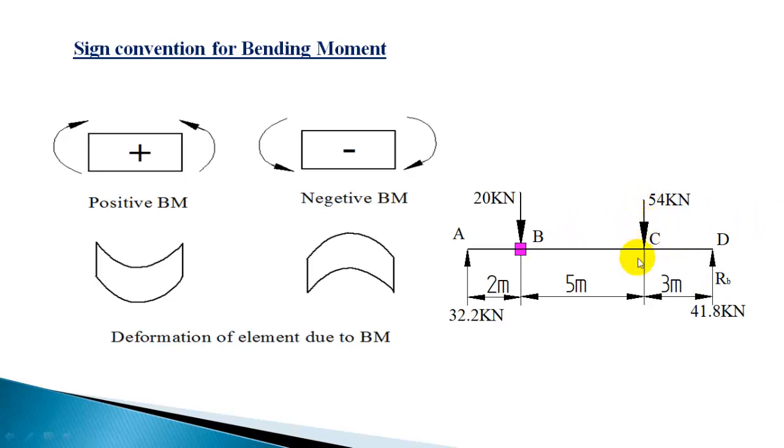So this is 270 and this is 336.4. Because they are acting in opposite directions, the resultant moment produced by these two forces with respect to the section will be 64.4 counterclockwise. So from here it is clockwise, from here it is counterclockwise. So 64.4 clockwise and 64.4 counterclockwise.